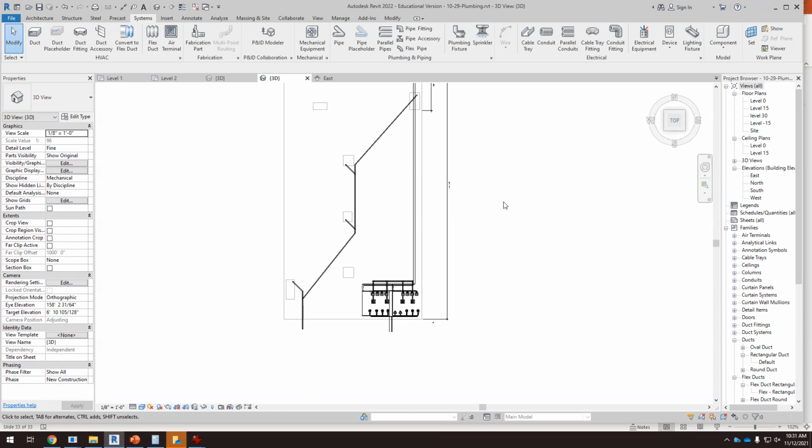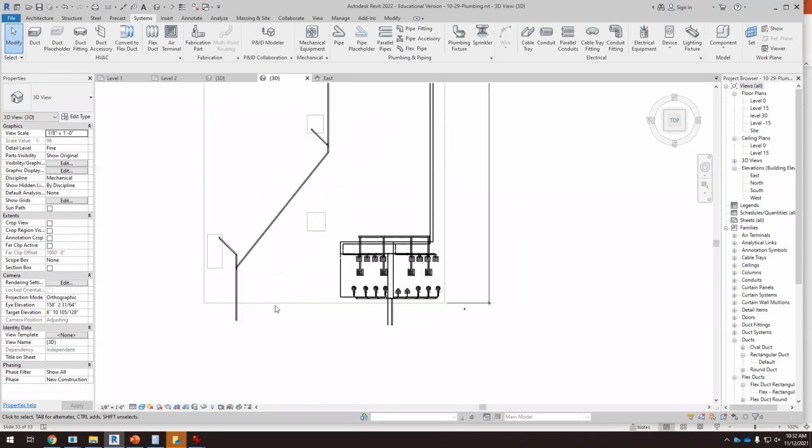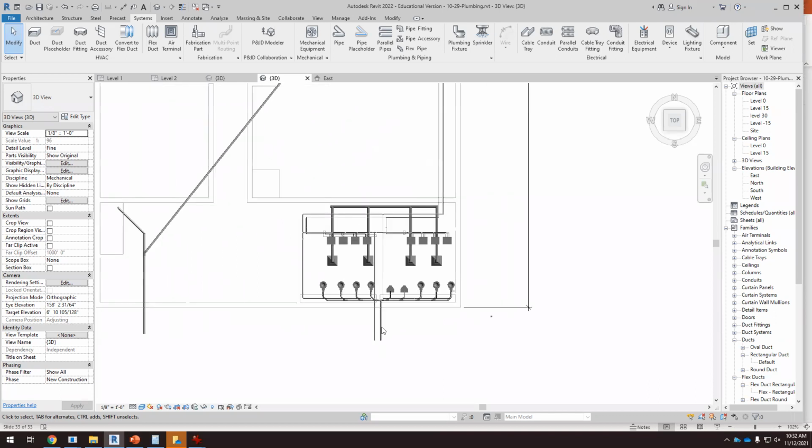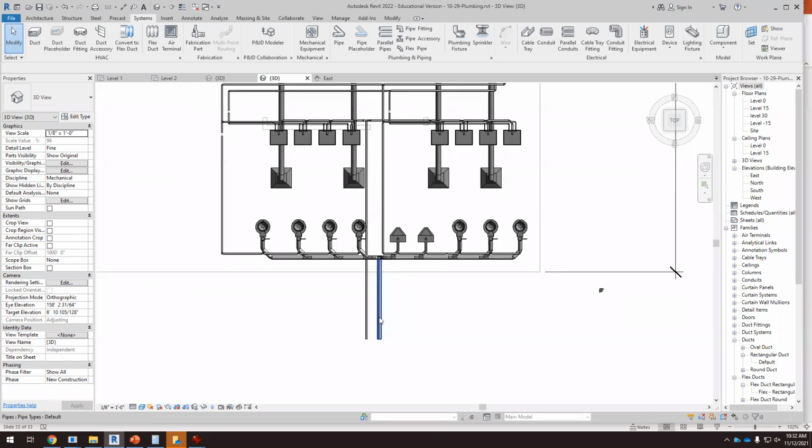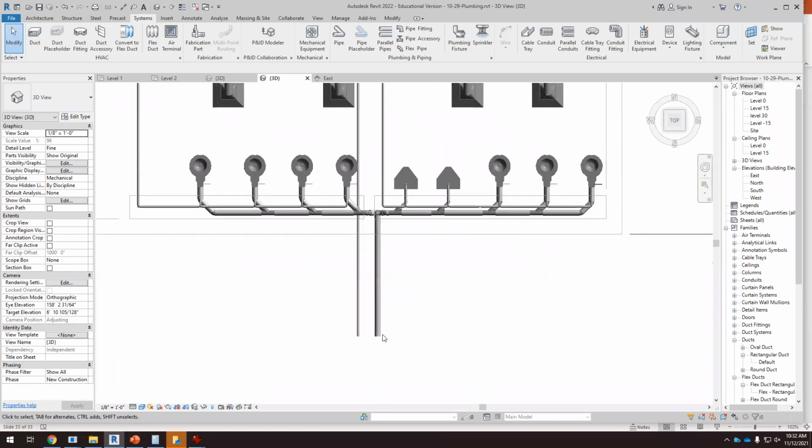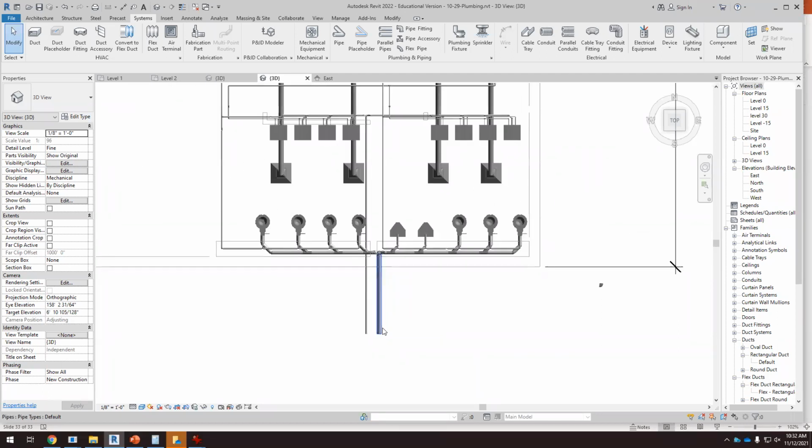And the important thing is that we have something for the black water that comes from the toilets. We have something for the gray water that can come from sinks or washing machines, dishwashers. And then we have something different for the rainwater. We could eventually connect the gray and the rainwater. Get used to separating, or not connecting, the black water that comes from the toilet with the other ones. Okay?